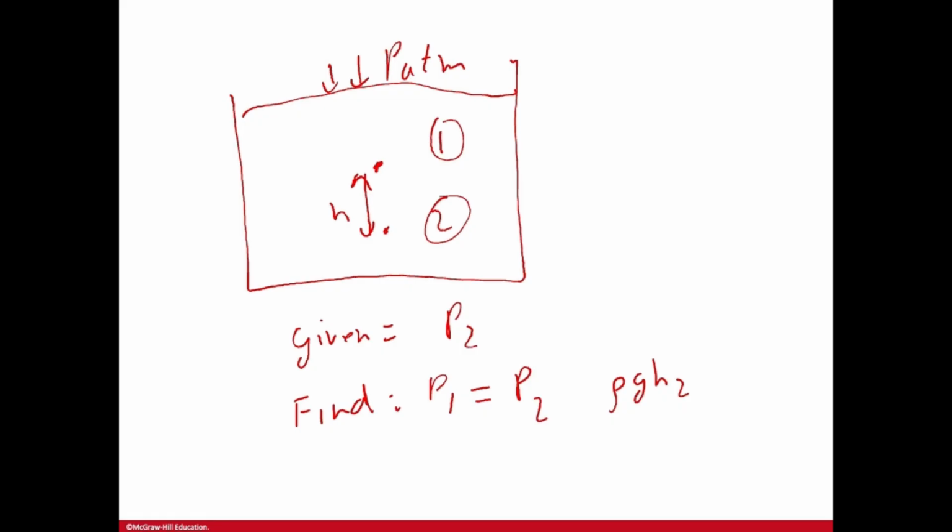Now even if you don't remember exactly what the signs should be, positive or negative, just think about it this way: is the point at pressure 1 above or below 2? In this case it is above 2. So will the pressure at 1 be bigger or smaller than 2? Remember again, pressure is just the weight of the liquid column.